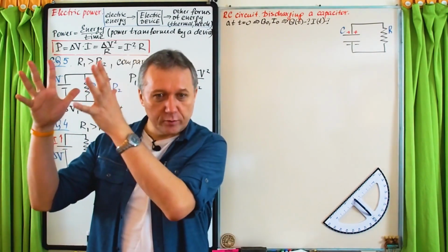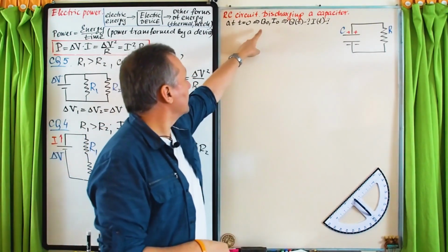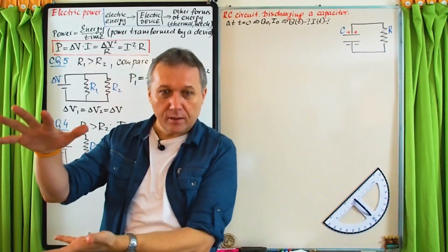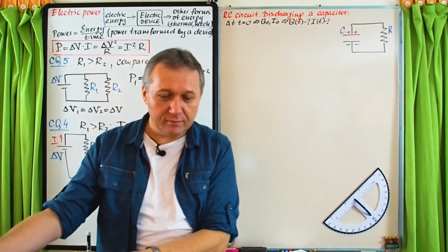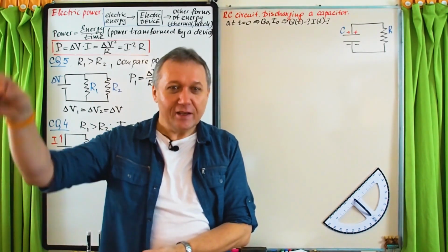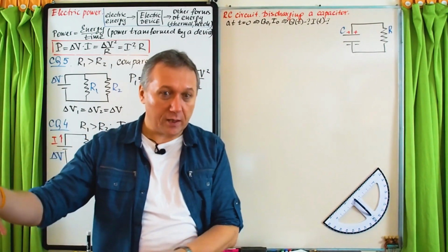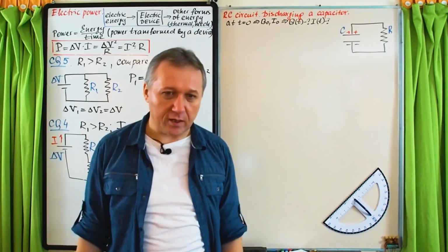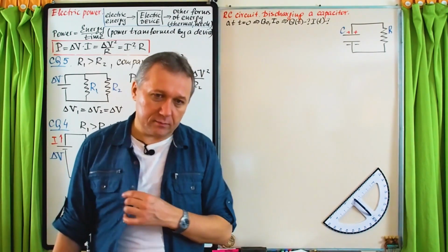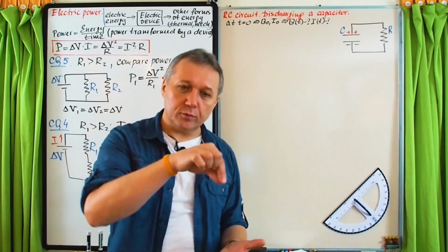What if capacitor is already full with the amount of charge Q0, right? Let's say Q0. And then you want to drain it. And of course, how can you drain it, right? Through the resistor, because if you just connect negative electrode of the capacitor to the positive electrode of the capacitor, right? Again, you can damage just the system. Current will be too large, and it's better not to do it. So it's better to drain it through a resistor.